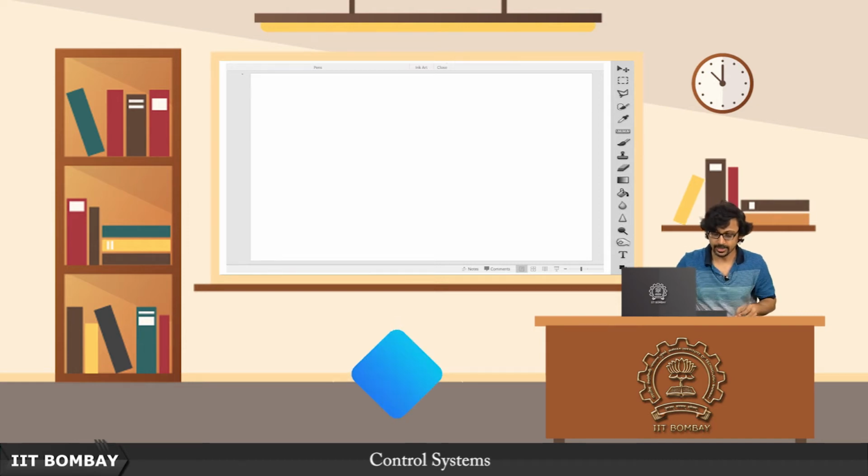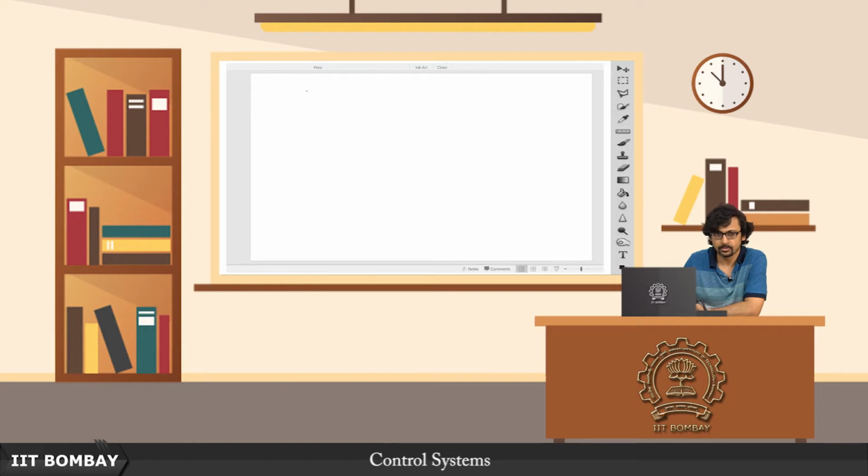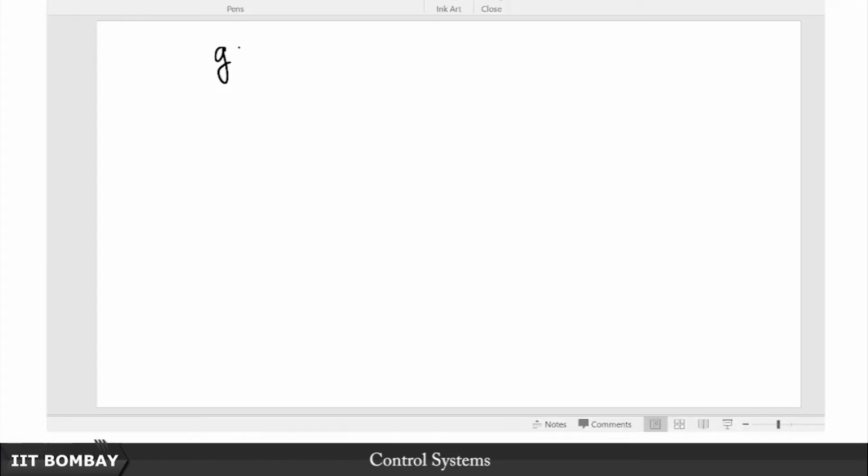Hello and welcome to today's lecture. So we ended the previous day's lecture by observing that if you have a linear time invariant system whose impulse response is characterized by a function such as this, then it is actually easier for us to deal with the Laplace transform of this impulse response, which we call G(s) and which has a specific name, known as the transfer function.